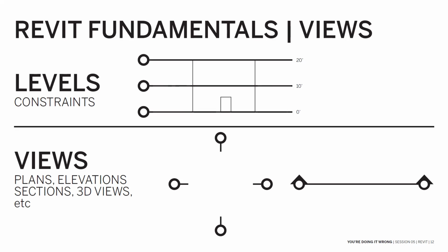And it's constrained to certain elements that are in the model. So one of those major elements is levels. And levels determine the height and placement of elements in elevation, and we'll look at that in a second. But it's very important to be aware at all times of the levels that you have and have created, and what elements are constrained to those levels.